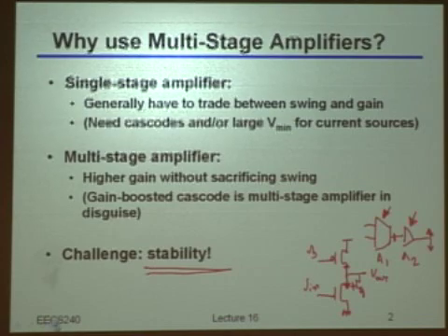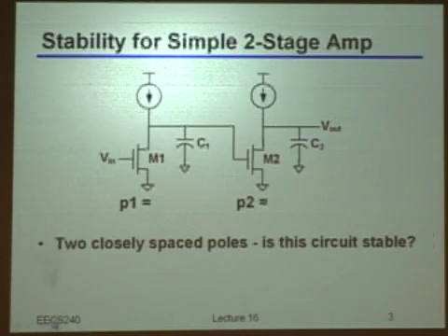we were saying, right? And so just to warm up, let's go for the simple case that we know already. So two common source stages, the very simplest case, in the sense that you analyzed this already in the past. Let's assume that I have here a common source that might be ideal, and so I will just place some output impedance here, R1, to model the output impedance, and then an output impedance R2 for the second stage as well. So, warm up. Where is the first pole located?